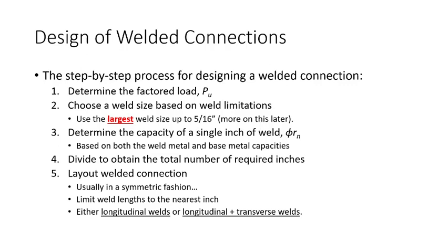that you need. Now for us in this class, when we lay out the connection, what we're going to do is limit our weld lengths to the nearest inch. Some folks do the nearest inch, some folks do the nearest half inch. I don't really recommend getting more specific beyond that. I don't think you need to be speccing out welds to the 1/4 inch. I mean, you can, but just for simplicity, the nearest inch would be fine. Usually you lay those out in a symmetric fashion, and I say usually because we can lay them out in a balanced arrangement as well.